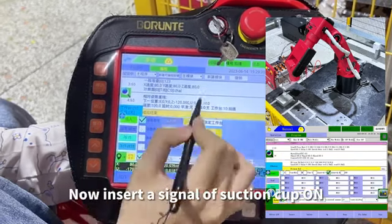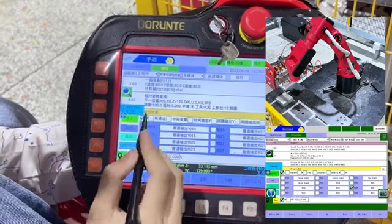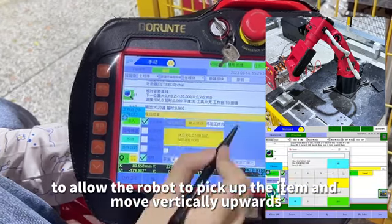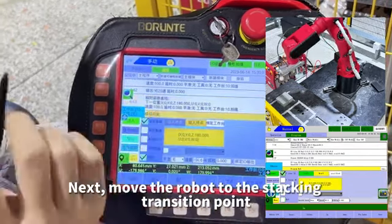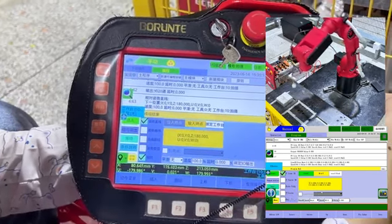Now insert a signal of suction cup on. Insert another relative function to allow the robot to pick up the item and move vertically upwards. Next, move the robot to the stacking transition point and repeat the previous operation.